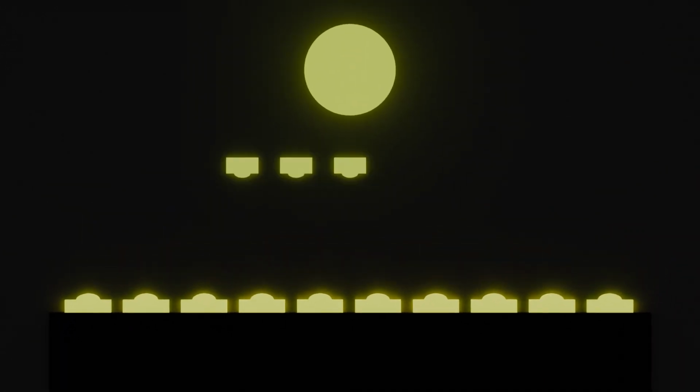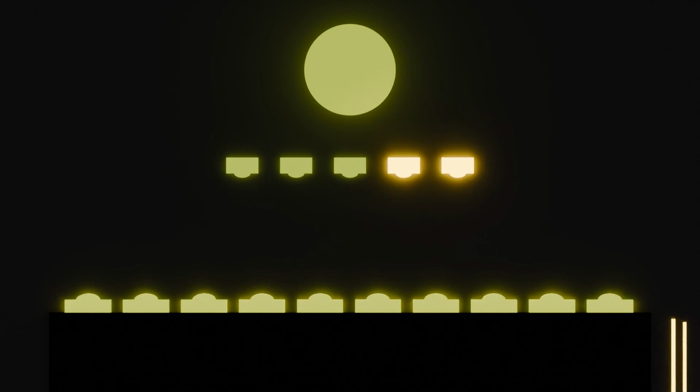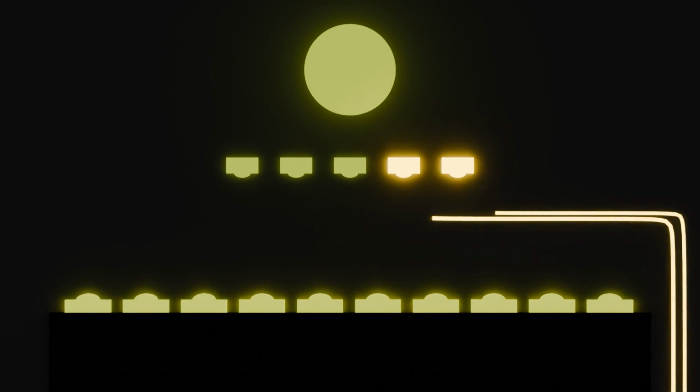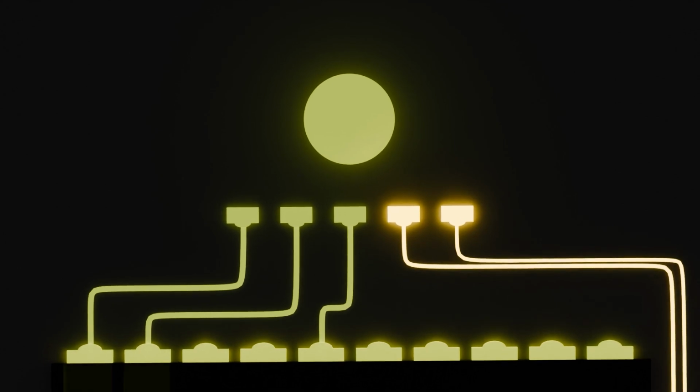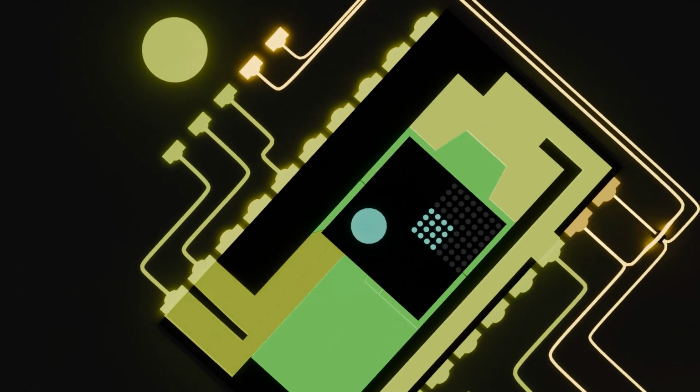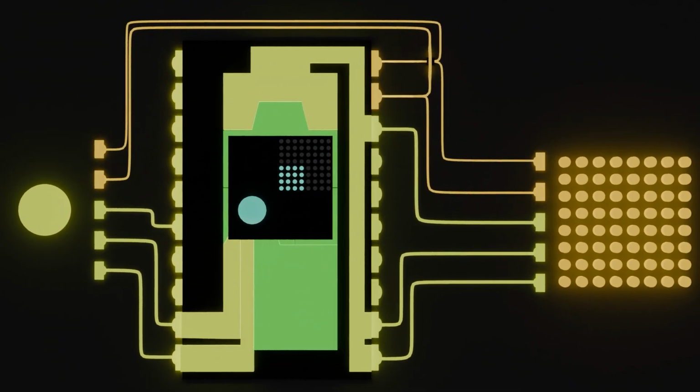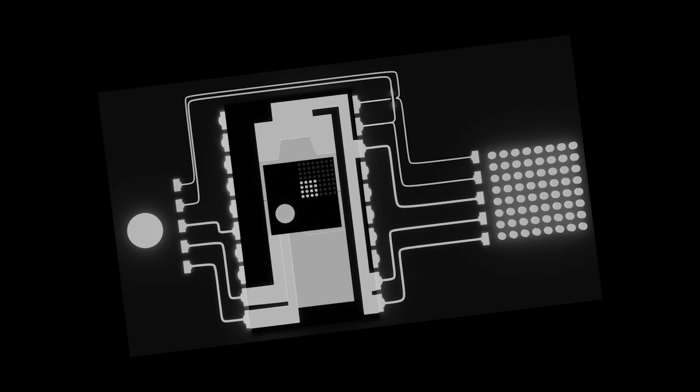For the joystick, it's even simpler. We've got 5 pins, and once again, 2 are voltage and ground, and 3 are coordinate in X, coordinate in Y, and button press. So now all we have to do is just get the input from the joystick back into our function, and just plug it in as the X and Y coordinates. And that's why breaking it into functions previously was so important. It's because right now we can just plug it in and that's it. That really is the entire thing finished.